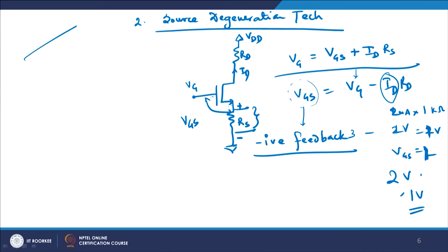So current is flowing, so this is basically at higher potential as compared to this, of course. As a result, this will reverse bias the source gate junction. So it's something like this. On the source side, this is N plus, let us suppose, and this is N plus drain side. I have a gate here, and then I have a metal contact here.